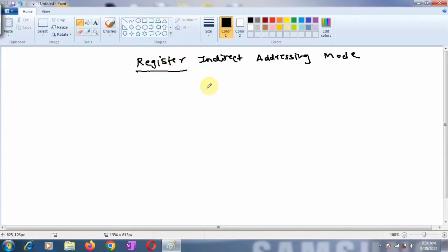is stored or placed. Now remember one more thing, that in case of a register indirect addressing mode, only two registers you can use, that is R0 and R1 register. So R2 to R7 registers cannot be used to hold any address of your RAM location in register indirect addressing mode. Now we will discuss the different examples, and one more important point here is whenever you write the name of the register in the instruction, then it should be preceded by one sign which is the @ sign.